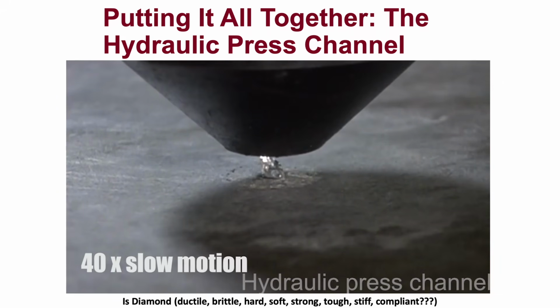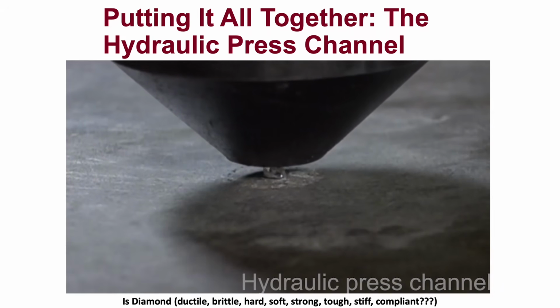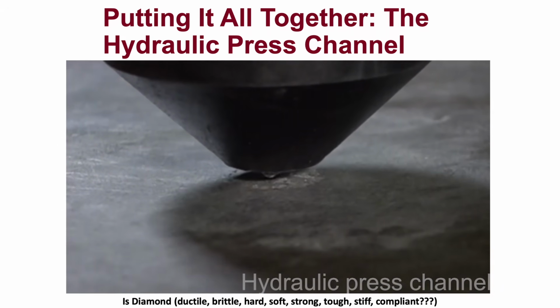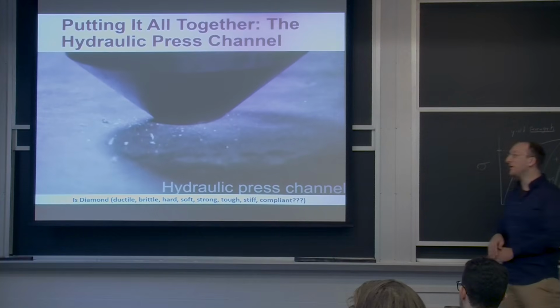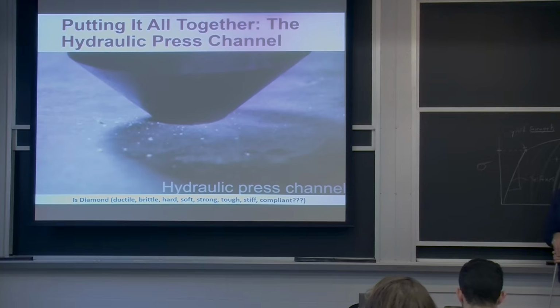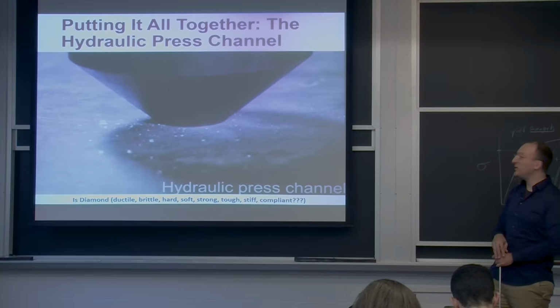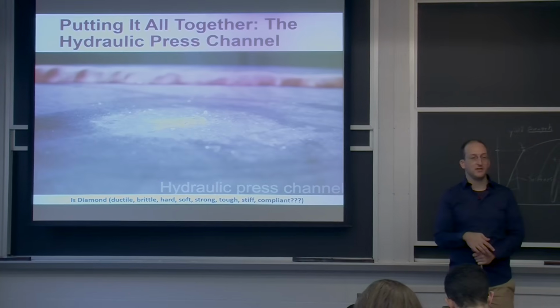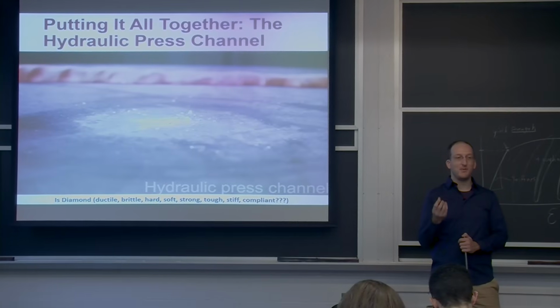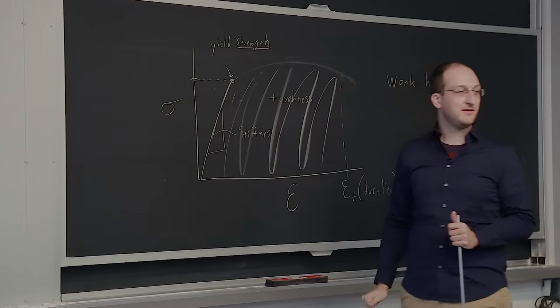They still have pretty big chunks though. Oh yeah, I could probably still sell those. Absolutely no deformation. Wow. It just rotates and explodes. Yeah, this would be a material that we would say has almost zero ductility. Wow. Despite being extremely hard, I don't know if there would even have been enough deformation to have a slight dent in the tool itself. There's probably a little hole where the point of the diamond poked in. But once there was enough stress on that diamond, its stress strain curve would look something like that.